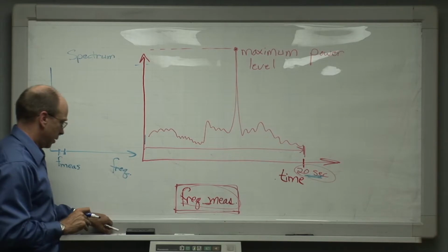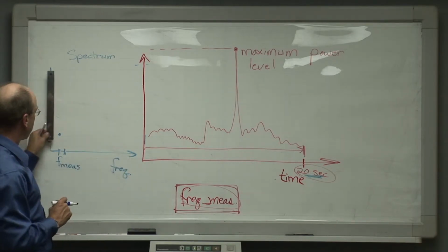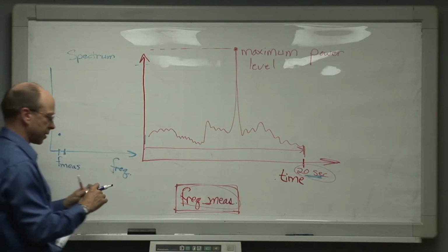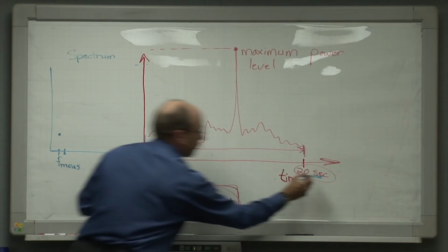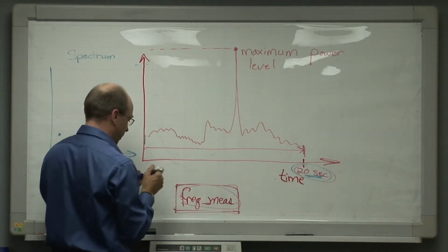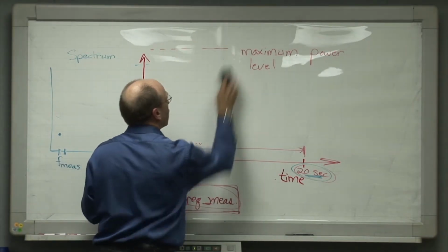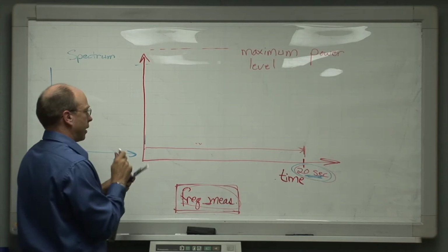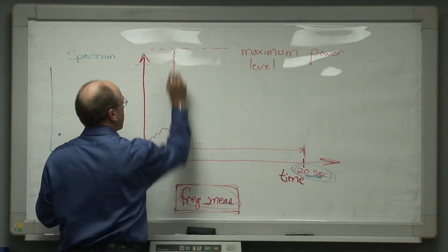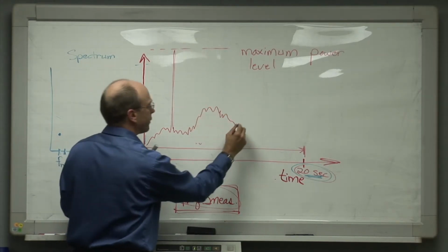We adjust the amount of attenuation in the front end of our measurement system, if necessary, to keep the radar emission within that magic dynamic range of the measurement system, and we wait for another 20 seconds. And when we do that on the second sweep across on the spectrum analyzer, since the first sweep now will be erased, we watch the spectrum analyzer run, and this time, by sheer random accident, that maximum level occurs almost immediately, and then we see some side lobe behavior like this.